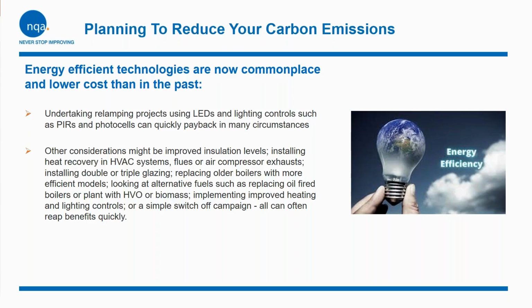He said the skylights and the roof were black, and we cleaned our skylights, so more natural light was getting in. They had reduced their electricity in that one shed, as they were all separate sheds, purely from cleaning and painting the place in a much brighter colour. It was quite a small investment, but with quite a quick payback time. So what I would always encourage any organisation is that it doesn't have to be a massive amount of capital investment to get quick wins.